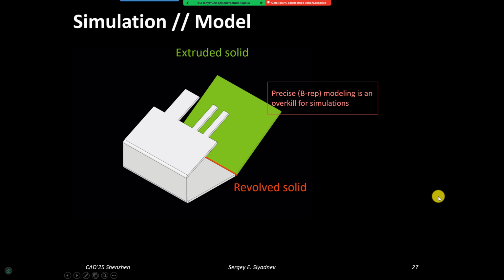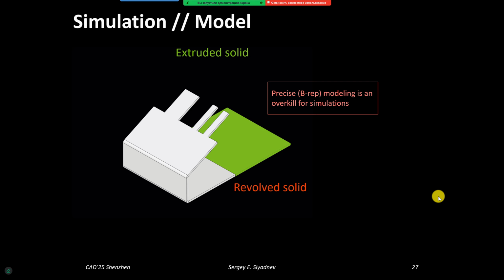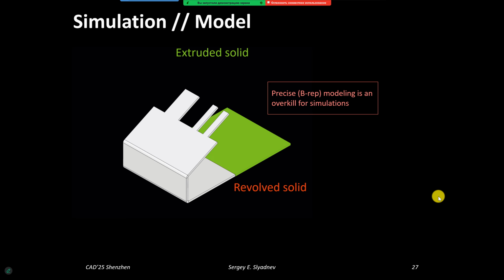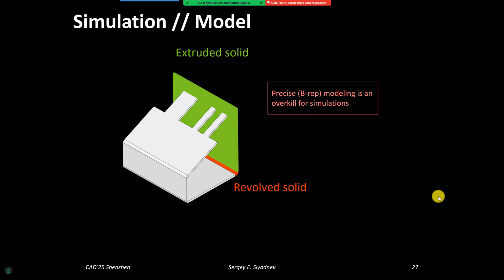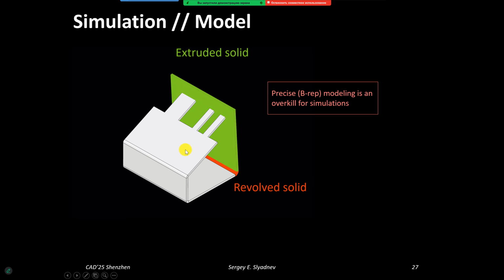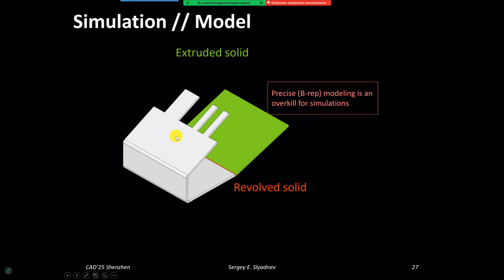One question though is that at each stage in this algorithm we have to move flanges around. So we have to do this local folding and unfolding. And basically the BREP structure that we have in the beginning after we imported the STEP file is not that flexible. So you cannot easily modify it. One way you can facilitate this folding and unfolding mechanics is you defeature the bend that you are looking at right now.